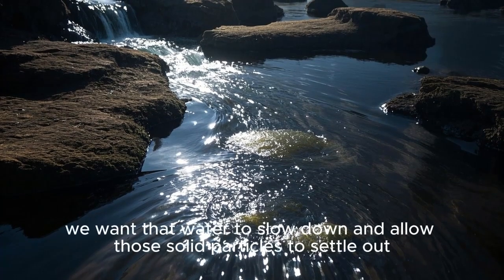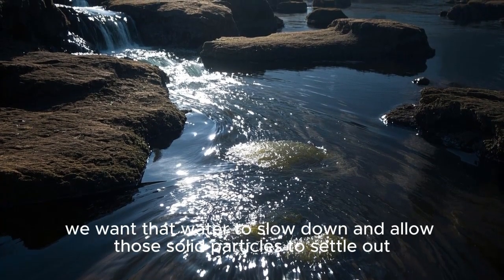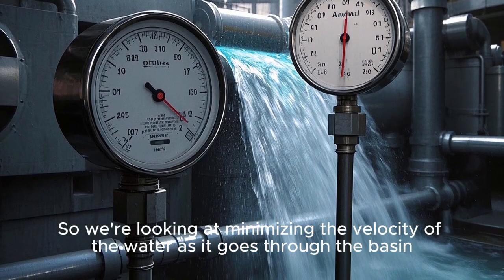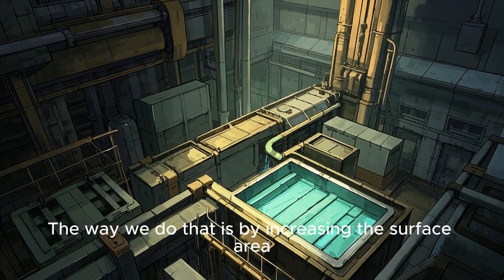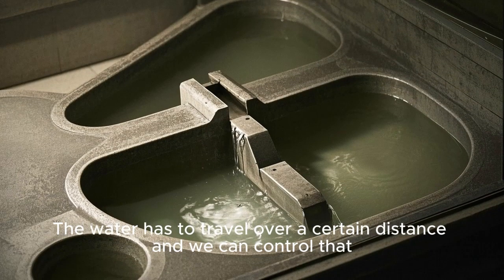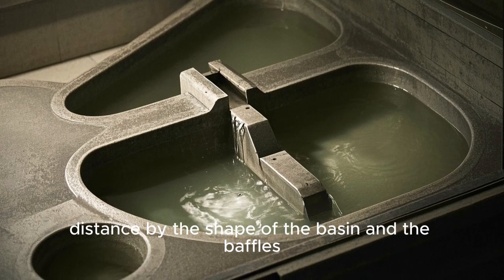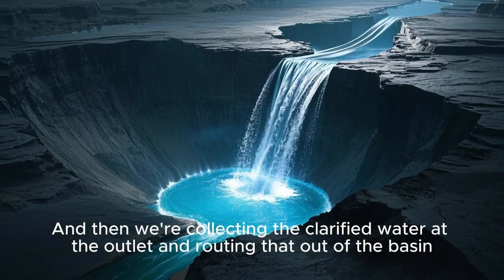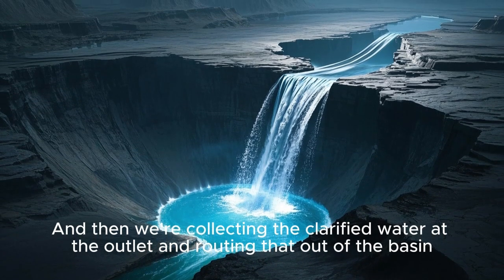Once it's spread out, we want that water to slow down and allow those solid particles to settle out. So we're looking at minimizing the velocity of the water as it goes through the basin. The way we do that is by increasing the surface area. The water has to travel over a certain distance, and we can control that distance by the shape of the basin and the baffles, if any, that we put inside. And then we're collecting the clarified water at the outlet and routing that out of the basin.